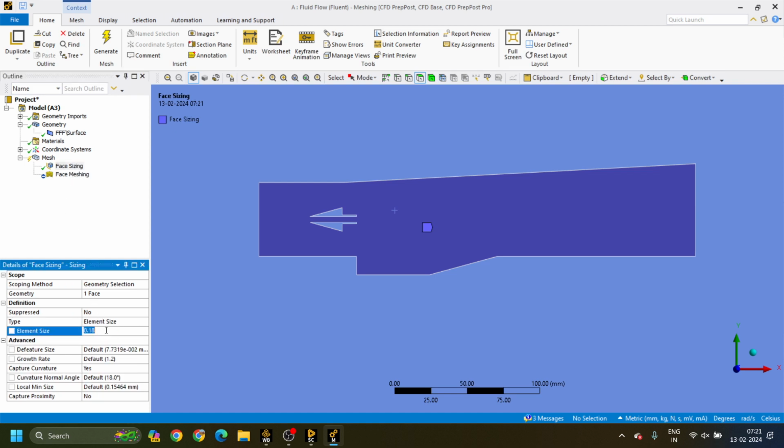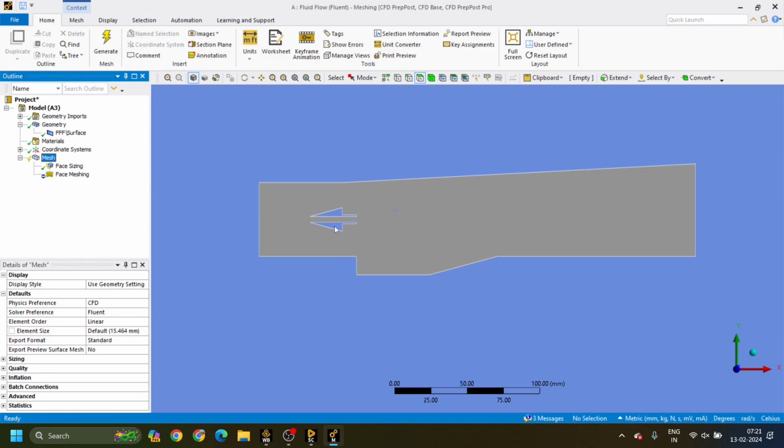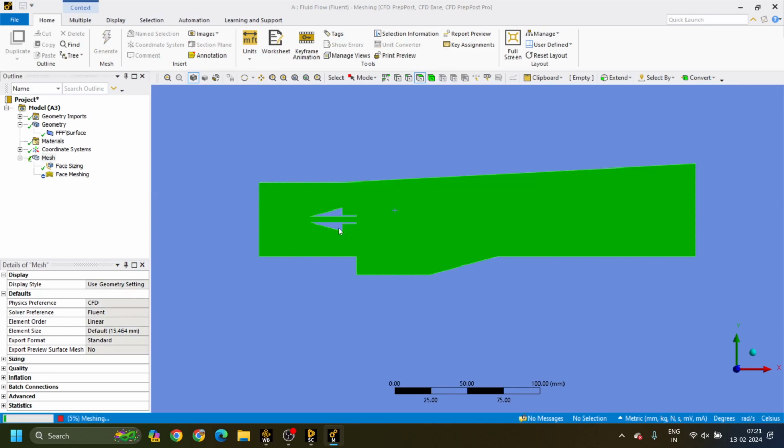At how much mesh size I kept, initially I kept 5 mm, now 1 mm. I can keep 0.9 mm in order to show you more clearly. Then we can go more and more down, like smaller mesh sizes such as 0.14, 0.1, 0.2 mm.